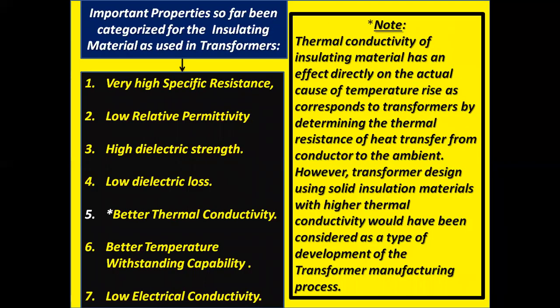Important properties so far been categorized for the insulating material as used in transformers. One, very high specific resistance. Two, low relative permittivity. Number three, high dielectric strength.